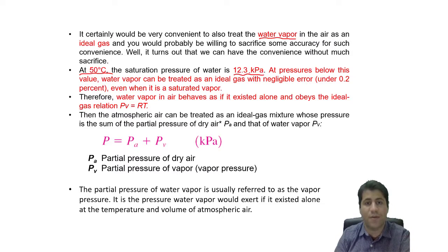This can come from the thermodynamics table. You can find it in table A4 or table A5. You can find the saturation pressure for this temperature.